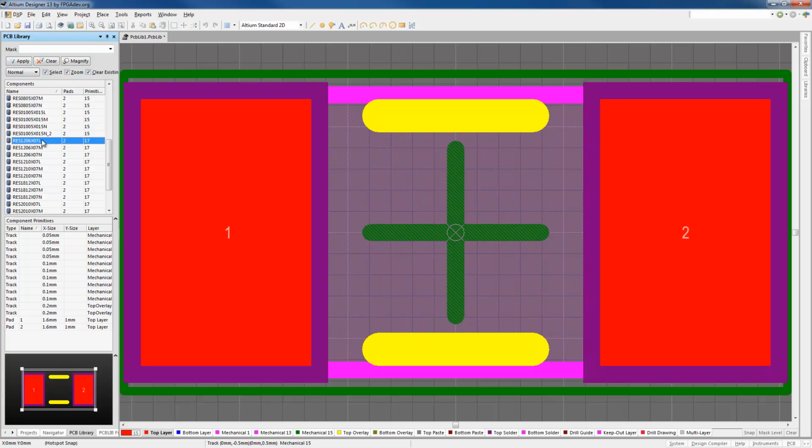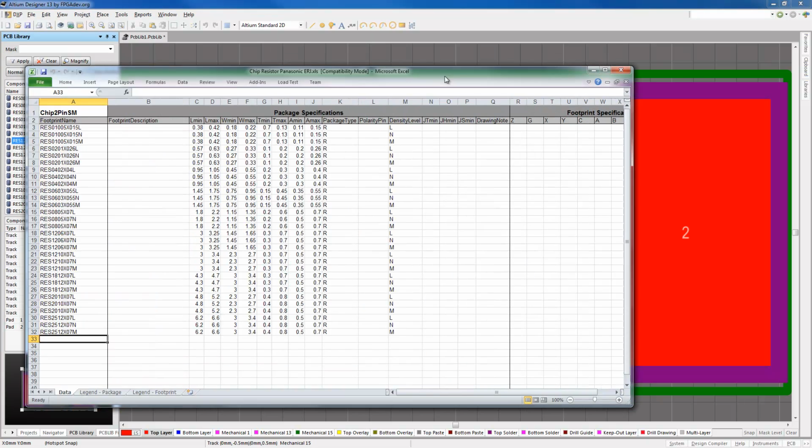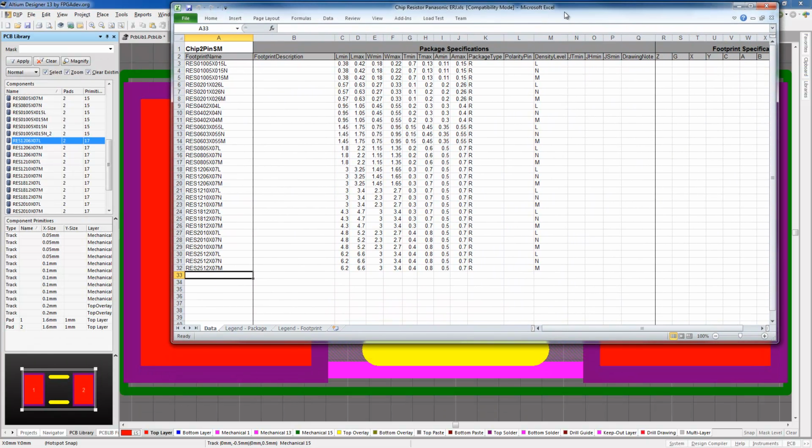There is one other thing that should be mentioned over here as well, and this is one of the things that you may want to consider. These names over here were picked because these are very common names that are used by the IPC standard, especially in the United States. You can use the millimeter version of it, however, a lot of people know it as 0805 or they know it as 0402, so that's why these were set up accordingly. And again, because these names were in here, that's what Altium took. If these names weren't here, these would actually be put into the millimeters.